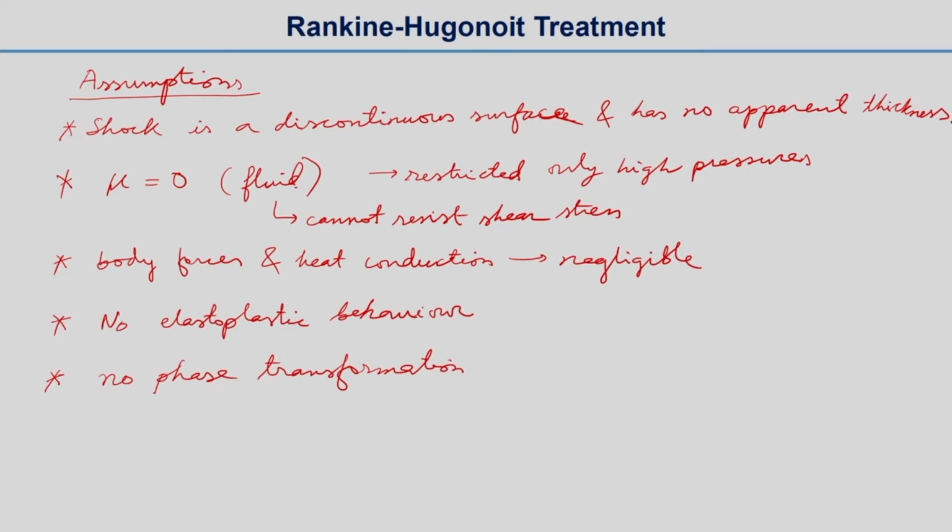And also a fundamental requirement of the stress wave, the shock wave, is that the velocity of the pulse U will increase when the pressure increases, which we already discussed. So the velocity of the pulse U will increase with increasing pressure.